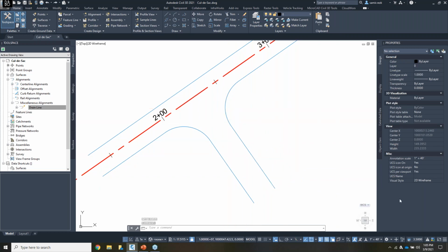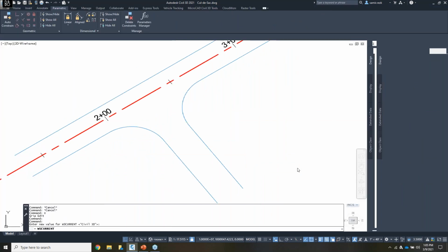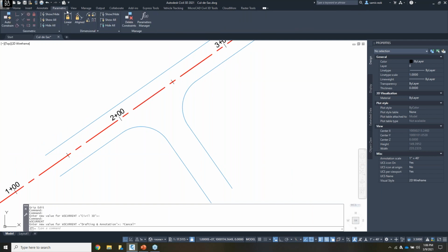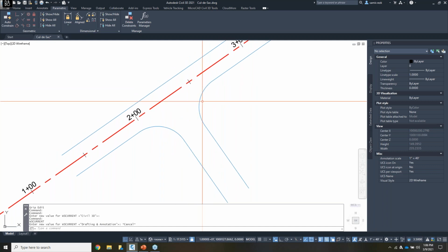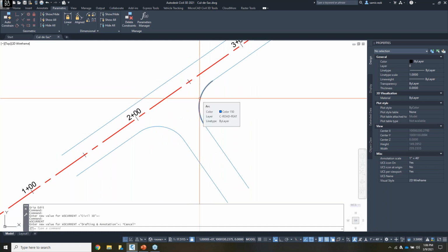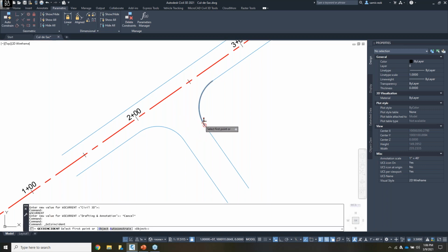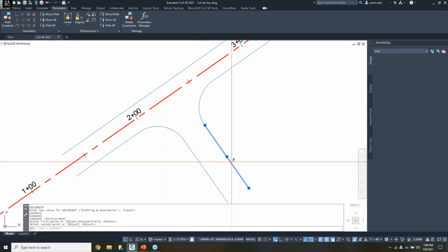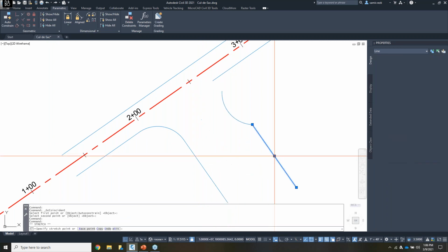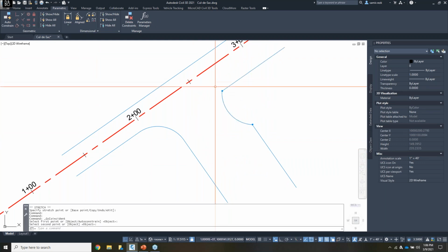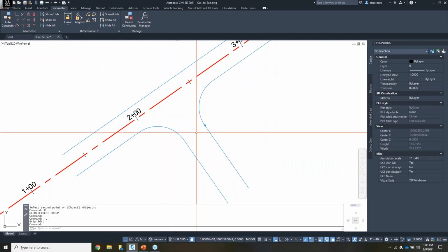So if I go into the drafting and annotation workspace, that's the AutoCAD workspace, you can see that we have a parametric tab. So this is my focus today, this parametric tab here. Once we have geometry drawn, we can give it constraints on how it behaves dynamically to other things. For example, I can apply a coincident constraint between those two objects, and now when one object moves, my arcs move with it, and I can keep doing that until I get something that looks like what I wanted to see.